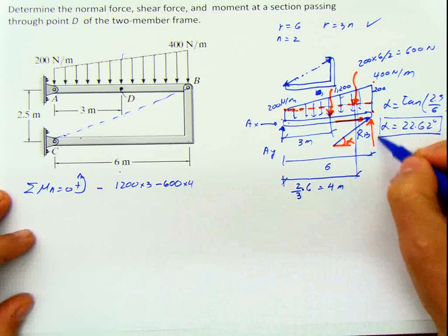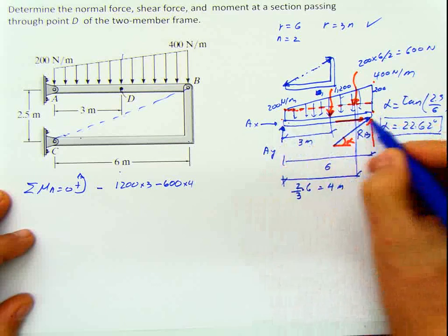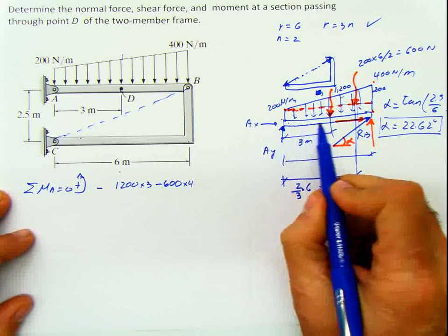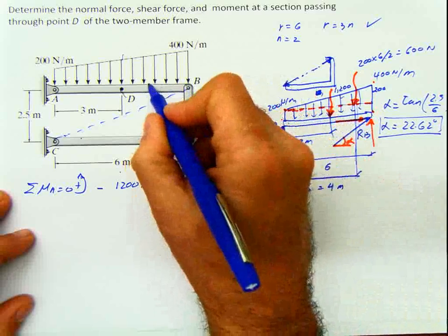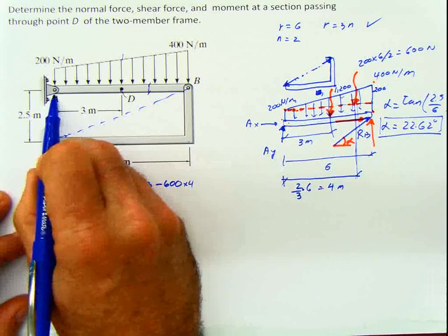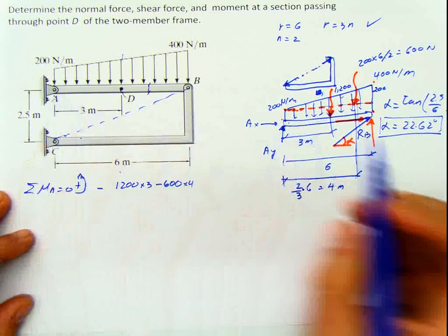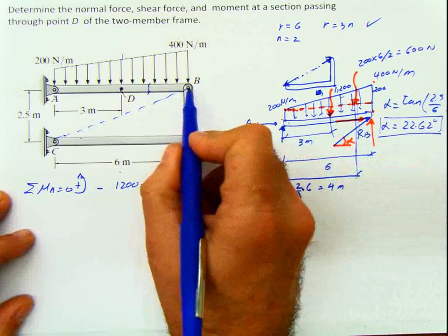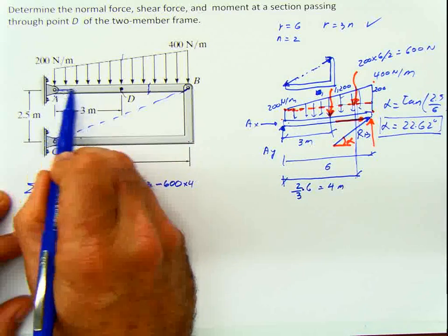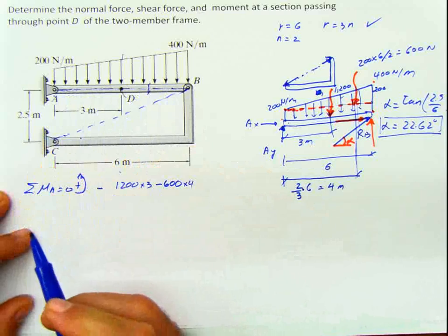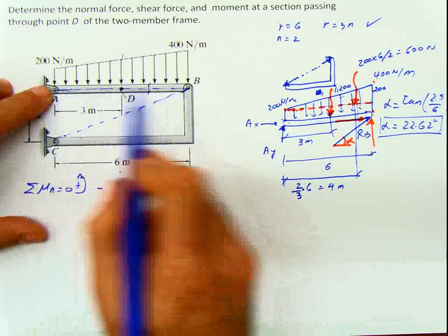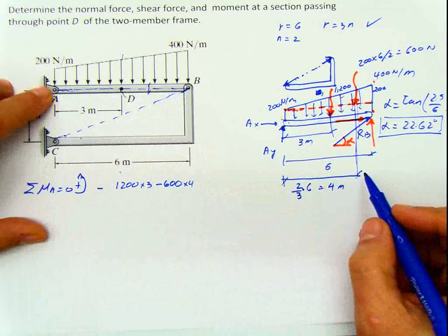And then I have the vertical component of RB. The horizontal is passing through the point, so it doesn't produce any moment at point A, because it's passing exactly through here. I don't have this thickness. If I had this thickness and the problem made a statement about it, and the point A is below, or above, then it would produce a moment. But in this case, the load is applied exactly at the center, where the support is also at the center. So be careful with those distances. Sometimes that distance has to be taken into account, but in this case it's obvious that it passes through the same axis. So we don't have to take that horizontal for anything.